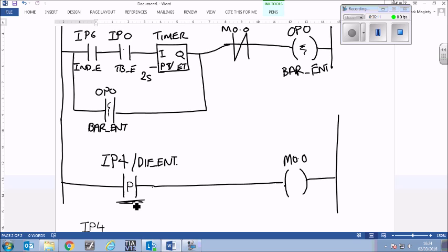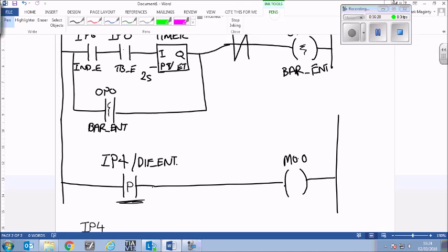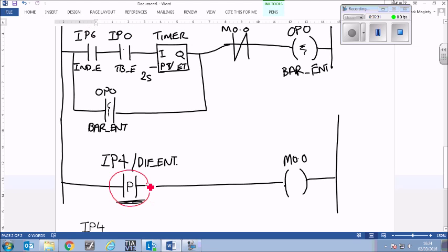So the car now travels through, it enters stage 4, and the car now clears the beam of light from the sensor completely. The sensor suddenly turns on, so it goes from off to on, which means this here becomes active and provides a 1 out, which turns that on. This opens, and therefore that would turn off, that turns off, and your barrier goes down, and your car is now clear of it.